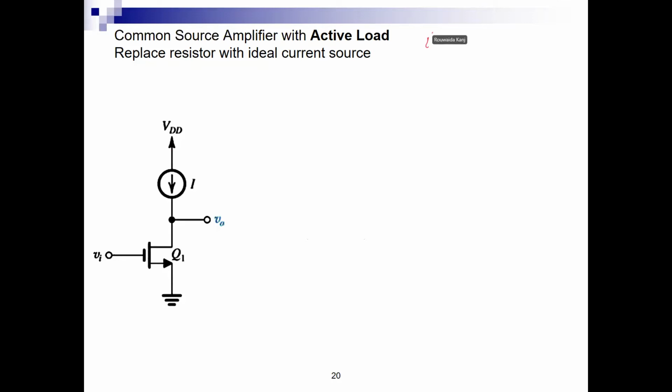So the ideal current source in small signal analysis, what do we replace it by? This is DC, we said they are set to 0. Right? Thank you Ibrahim. So they are set to 0. If it is a voltage source it becomes a short, like VDD, and if it is a current source it becomes open, because its model is R infinity.